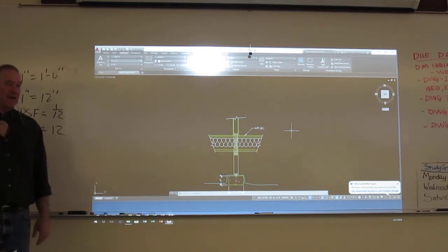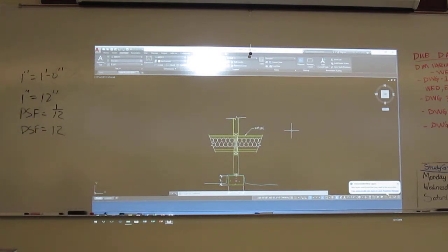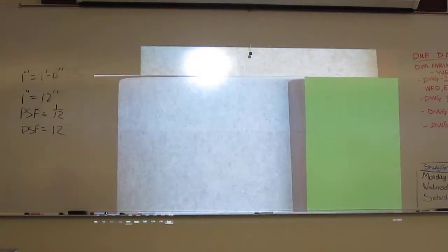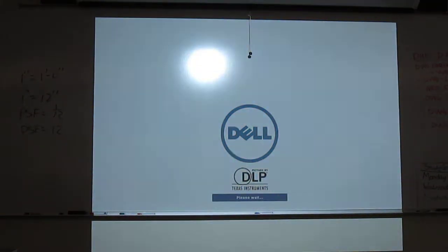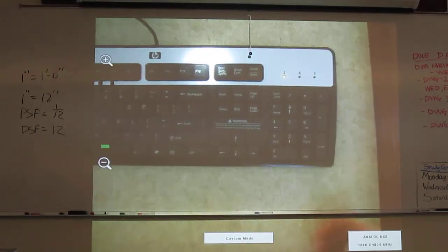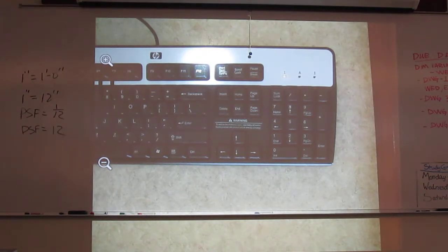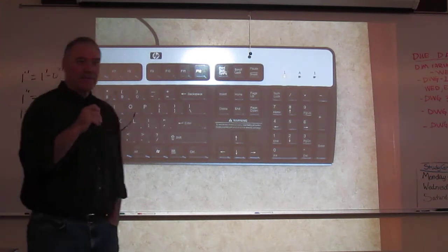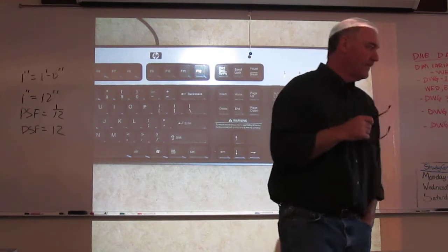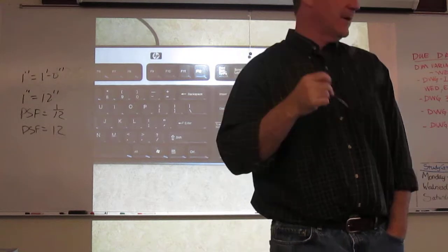Now, some nice things about the artstyle.shx font. Okay, go ahead, and if you got this drawing up, I want you to pop an MText box open somewhere. I don't have it on here, but I can show you the keystrokes. So just make sure your text style is set to Arch 1. And then do MText and make yourself a box so you're ready to type.